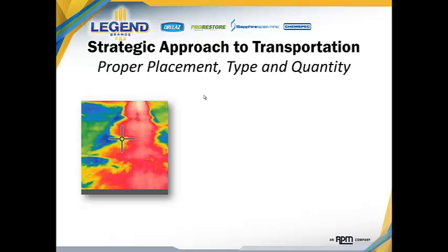And taking a look at some of those technologies, here is an example in thermal imaging of an analysis that we've done here at Restoration Sciences Academy on different air moving technologies. What you're looking at in the thermal imaging are areas of rates of drying, if you will, and the red to white areas represent a location where drying has been very successful because of an air mover that has been placed at the very top of the image. So the air mover is placed in this location, and it's blowing air out across this surface that has been wetted. The areas that are blue to green are areas where there is not a lot of successful drying.